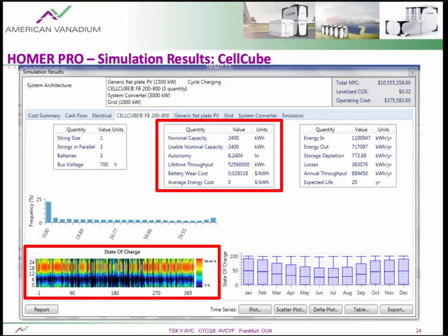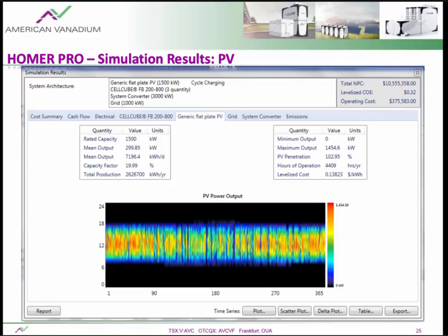Now generally I look through the PV tab as well, and also the grid tab, just for the DMAP, as a logic check on the performance of the systems. For the PV, it's running as expected. There's a lot of sunlight starting at around 8 and peaking at around 12 and dipping right before around 4 to 5 o'clock, and that's when you'd want the battery system to kick in.